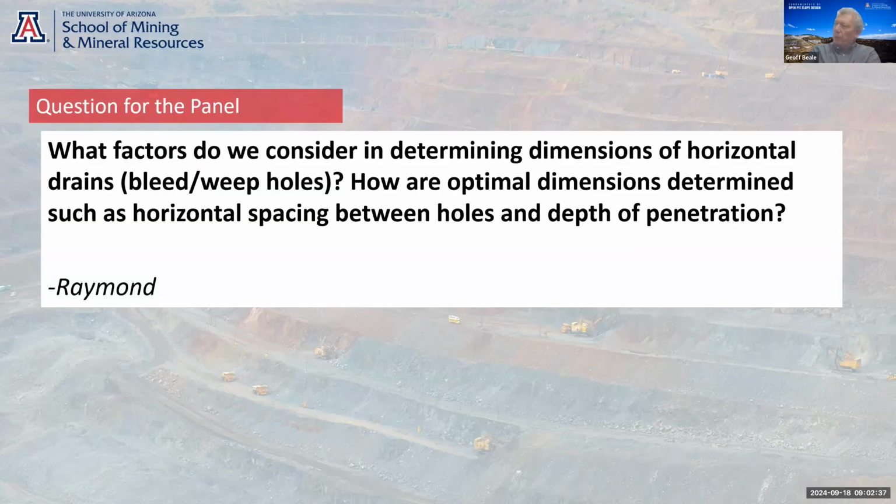I mean, weep holes, we're starting to put those into a lot of situations where we have dilated foliation or dilated structures parallel to the slope. And there are several sites involved where we've got more conventional horizontal drains, which are 200 meters long, for instance, to depressurize structures deeper into the slope. But in addition to that, we'll put in 5 or 10 meter deep drains just to get water from the blast damage zone.